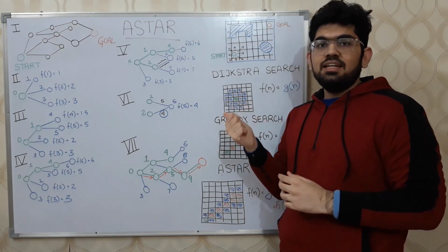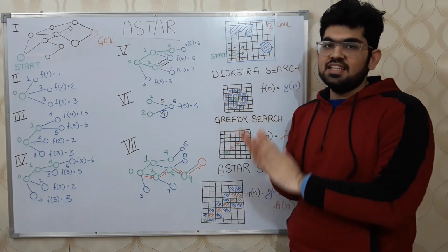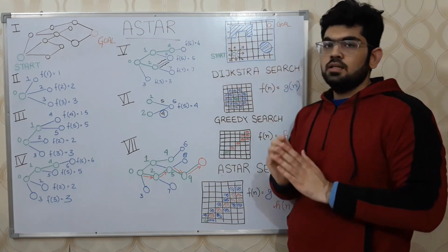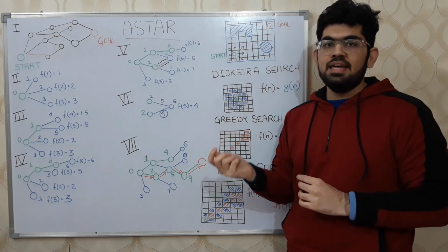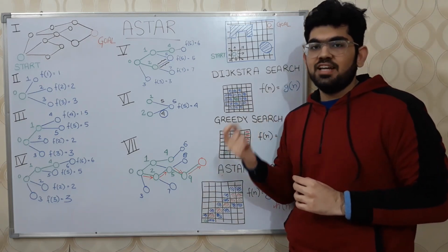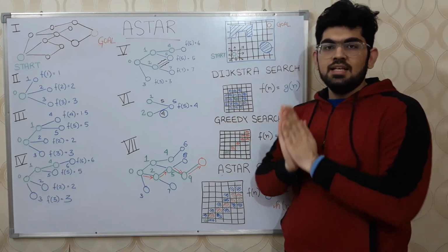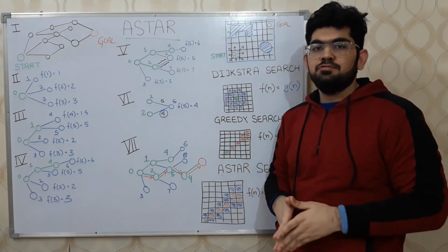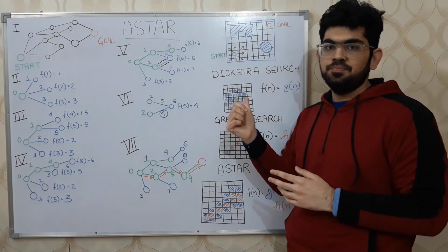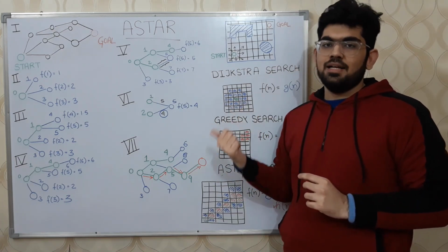The cells of this grid can be considered as the nodes of the graph, and the neighbors of any general cell, as we can see over here, will be connected by edges. Hence, from a graphical perspective, at any point of time, a robot can only move to its neighboring cells. Once a path planning algorithm has found a set of cells that the robot can go through to reach the goal position, a different path following algorithm can be employed to follow that path.